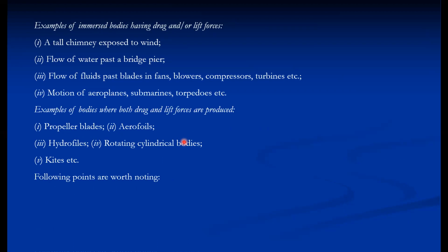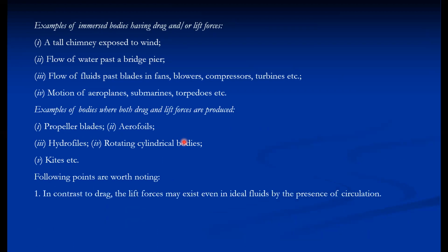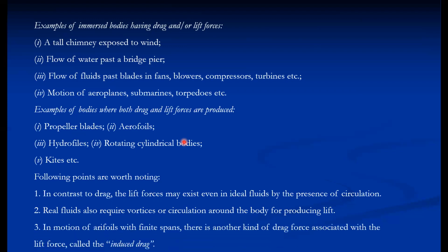Then the following points are worth noting in the case of drag and lift. In contrast to drag, lift forces may exist even in ideal fluids by the presence of circulation, but drag force is not present in an ideal fluid. Real fluids also require vorticity or circulation around the body for producing lift. And in the motion of airfoils with finite spans, there is another kind of drag force associated with the lift force, and that drag force is called induced drag. So that is associated with the lift.